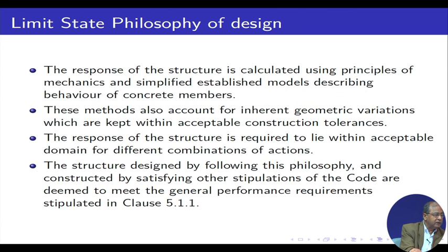So, I have simply read this out, but the basic idea is that we have different parameters, and for each parameter we have different partial safety factors. Not only that, the load combination depends on the simultaneous occurrence of the loads. If they do not occur at the same time, then we shall not take that combination with some other load.